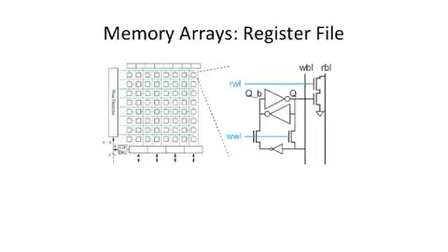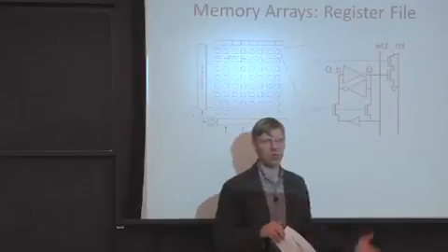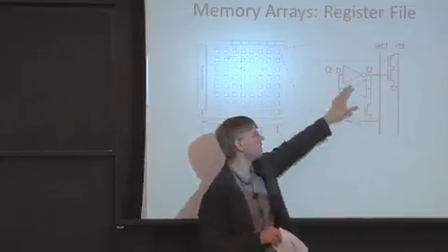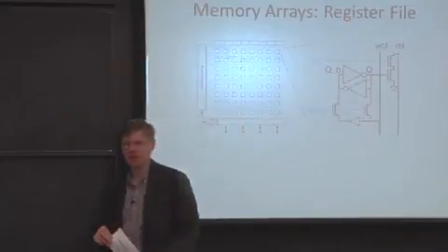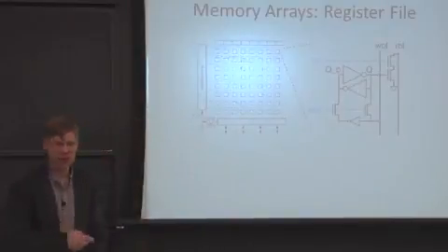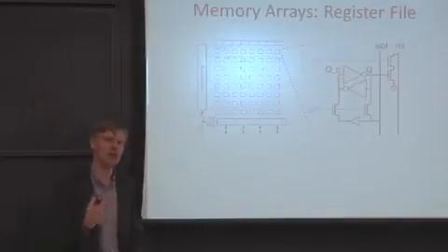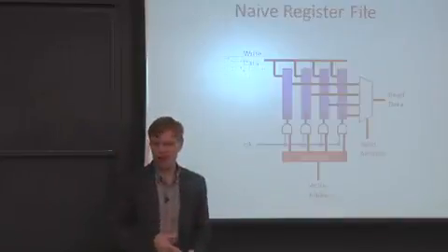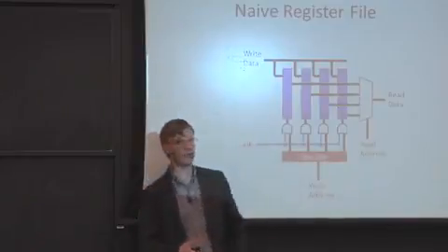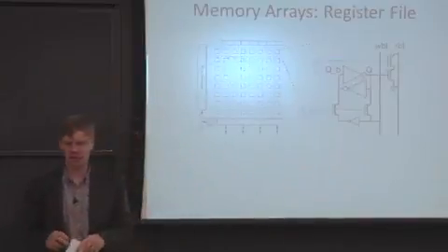And we're going to look at a memory array for a register file first. Let's look at a register file array and how you could possibly actually go build this, because it's a little bit different. We're not going to use fully complementary logic here for everything. Instead, we're going to start to transition to something where we will have more analog circuits connecting our bits to respective buses. And we're also going to change how we do the decode. We're not going to have a full multiplexer here or a full decoder here. We're going to split that into different portions.